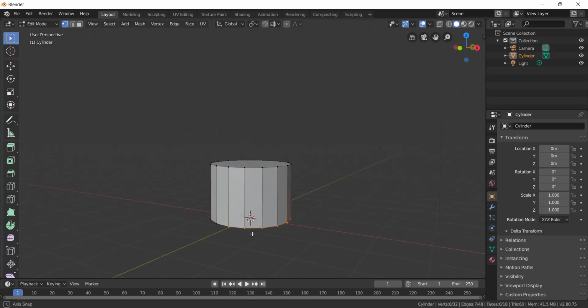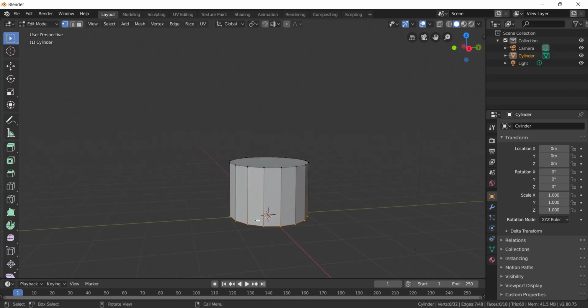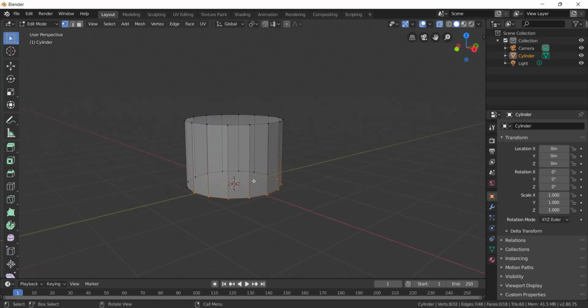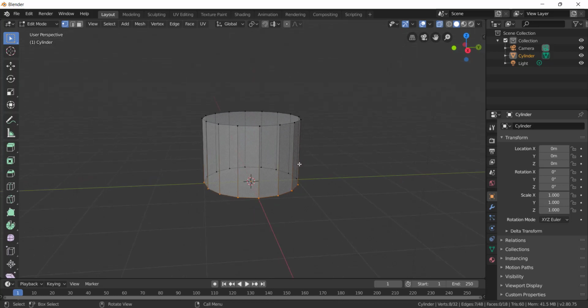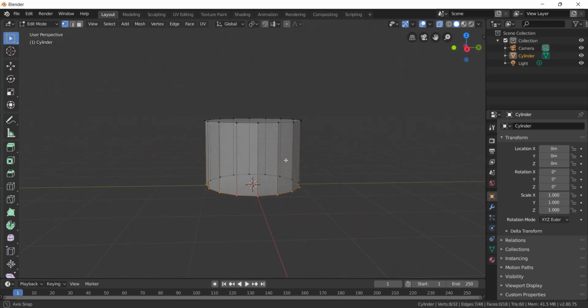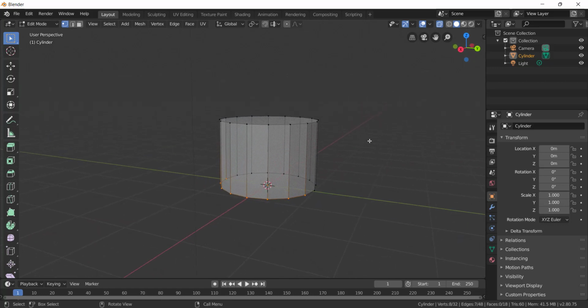not the ones on the backside. To select everything, you need to press Alt Z, which is the shortcut for X-ray mode. This is the X-ray mode. You can also go to wireframe mode, which automatically turns on X-ray, or you can stay in shaded mode and press Alt Z. After pressing Alt Z, whatever the rotation, whatever side you are on, you can select everything like that.